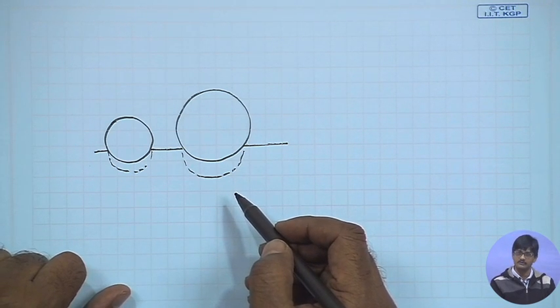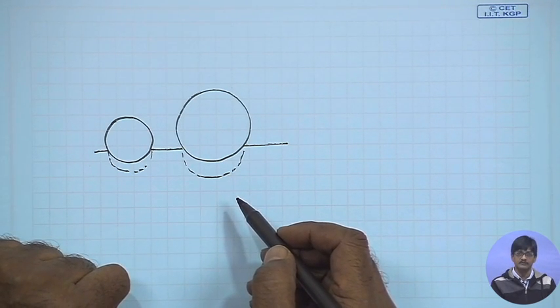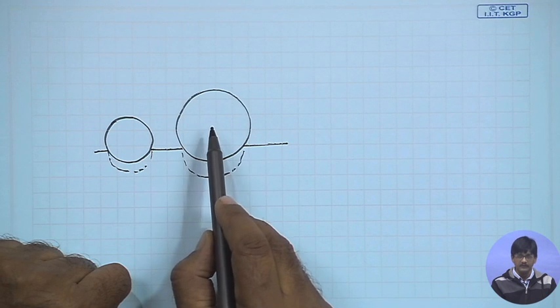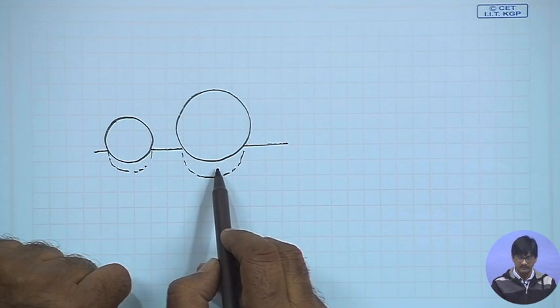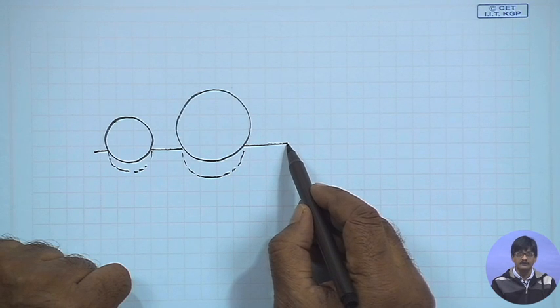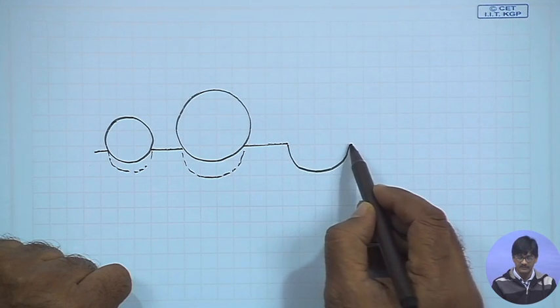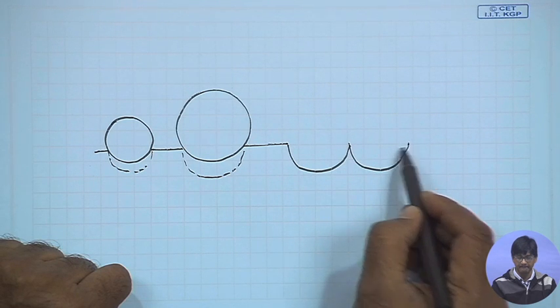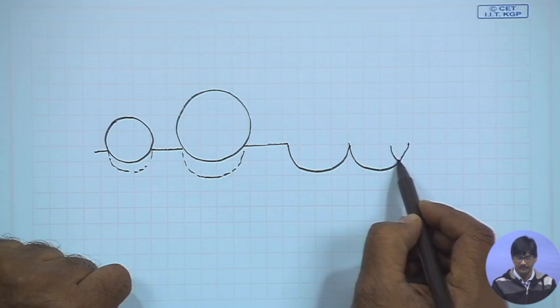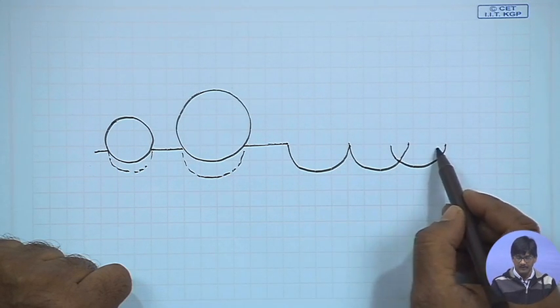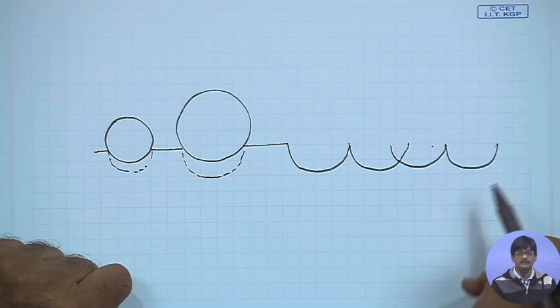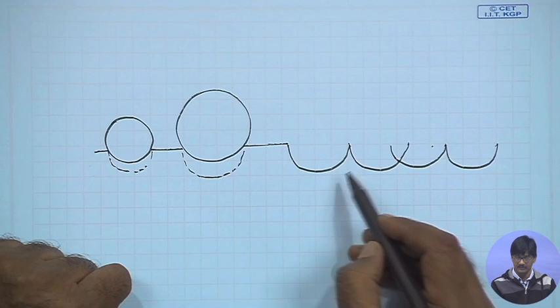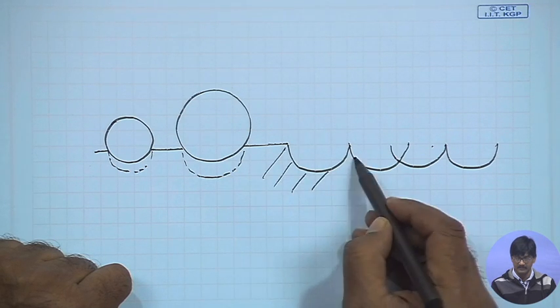Glass is brittle, tungsten carbide is brittle, and therefore, the larger the grain size, the larger will be the crater diameter. So, for larger grain sizes, we will have something of this type. That means overlapped large craters, so that ultimately the surface will come out like this.